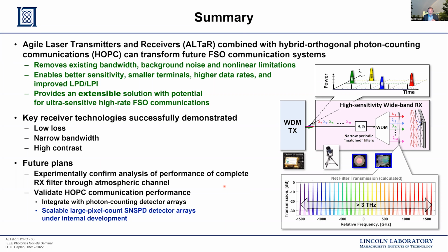The other benefit, though, is inherent in the waveforms that I've talked about. So pulse position modulation packs a lot of photons into a short time period, and then there's a long dead time. And then frequency shift keying now distributes that signal over a range of different detectors that can detect the different color elements. And so the basic spreading effect is to minimize the impact of any one pixel in your photon counting detector array. And so I welcome the opportunity to have some of the systems that I've talked about be limited by blocking losses, because that would mean we're talking about really high rate systems, very high photon fluxes, and the systems we're talking about perhaps 10, 20 gigabit or faster data rates of the type that I've surmised we can implement with these technologies. So thanks, another good question.